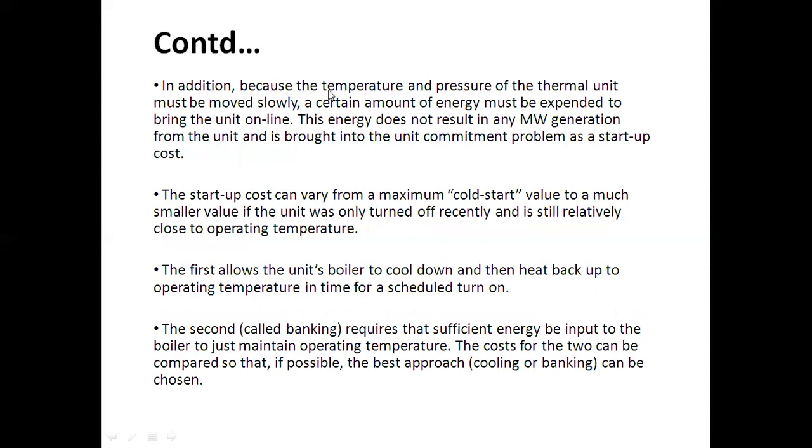In addition, because the temperature and pressure of the thermal unit must be moved slowly, a certain amount of energy must be expended to bring the unit online. This energy doesn't result in any megawatt generation from the unit and is brought into the unit commitment problem as a startup cost. The startup cost can vary from a maximum cold start value to a much smaller value if the unit was only turned off recently and is still relatively close to operating temperature.